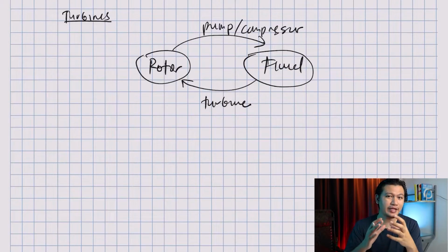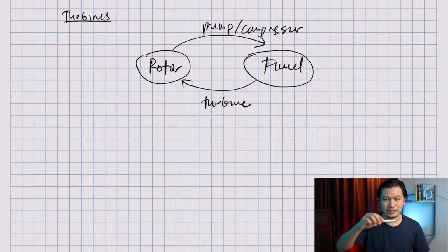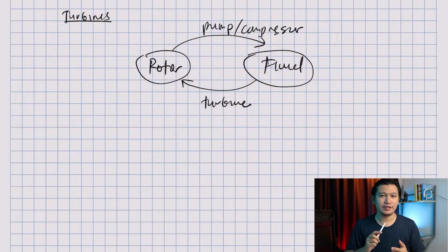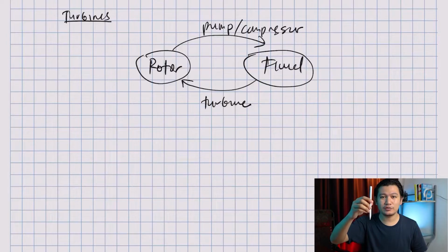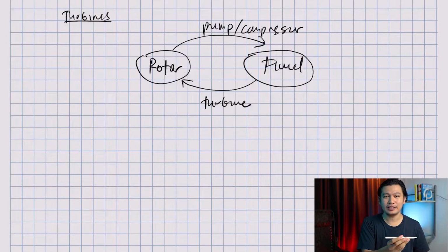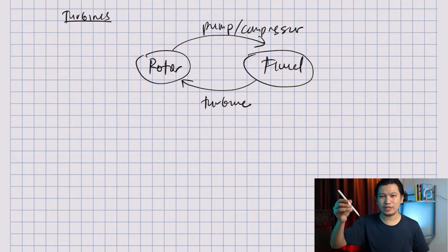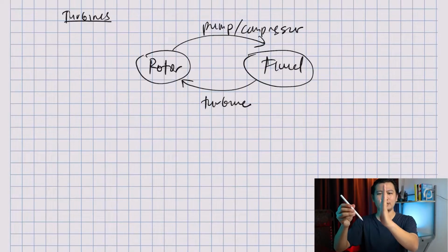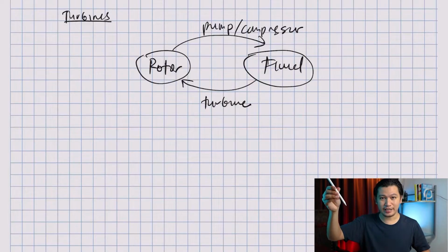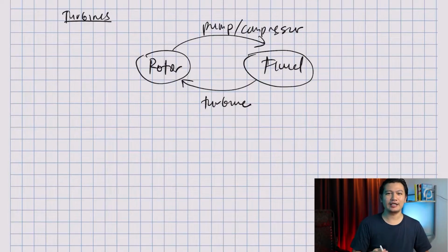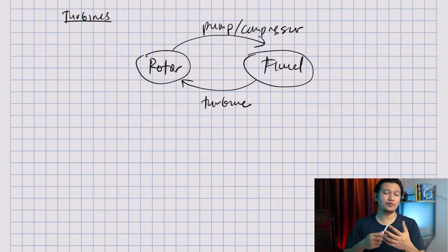And for turbines, there are many classifications that you can do. A turbine can be classified according to the shape. For example, it could be an axial turbine, where the water goes axially. Then it could be a radial turbine, where the water goes into the turbine and turns the direction to the axial direction. It could also be a mixed flow turbine, where the water comes in at an angle between the horizontal and vertical position, and goes out in the axial direction. And that is one way to categorize it.